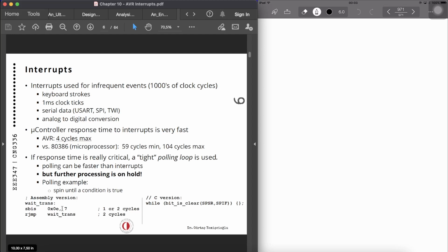So when we talk about polling versus interrupt, we can serve several devices while we are doing something else in microcontrollers, and we have to use polling or interrupts. Now, in the interrupt method, the device which is going to cause an interrupt sends an interrupt signal.